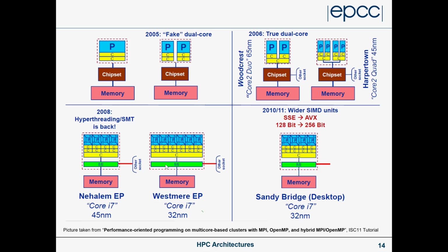So nowadays we're in this scenario where a processor will have a number of cores on it. Each one of those cores can run a number of threads. Each one of those threads can issue vector instructions, which also do fused multiply-add. So we have parallelism at the vector level, at the hyperthreading level, and then at the core level.